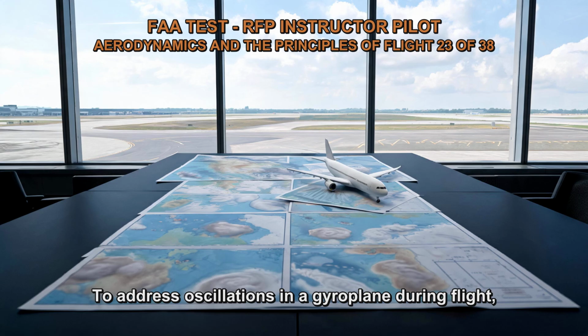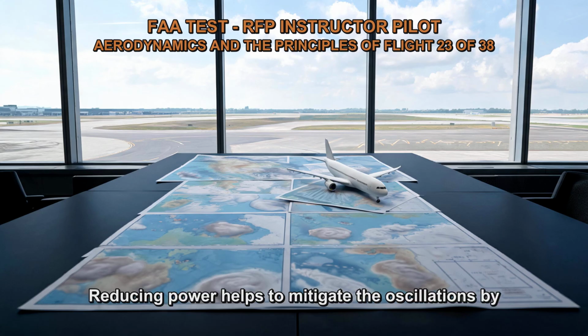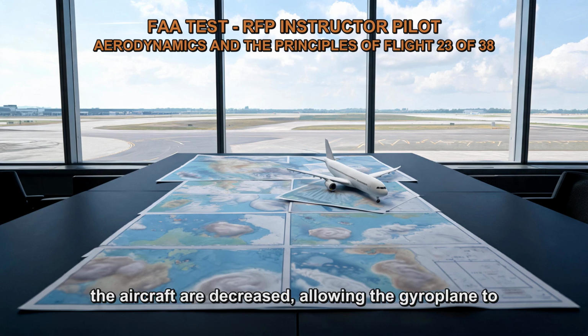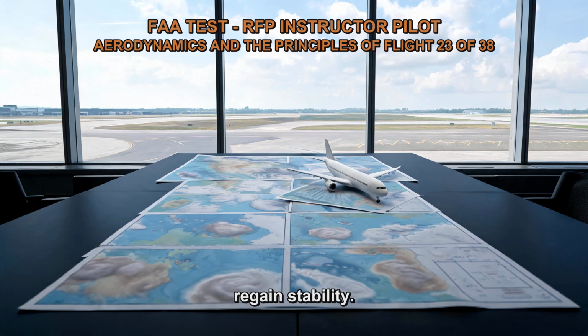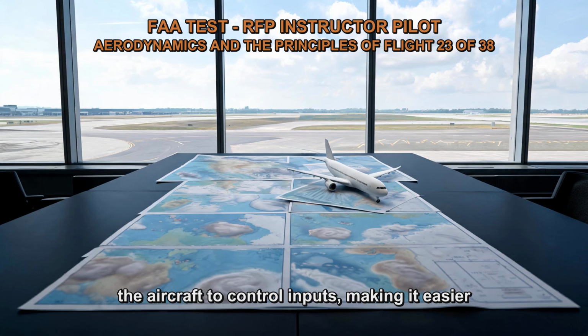To address oscillations in a gyroplane during flight, the first action that should be taken is to reduce power. When a gyroplane starts to oscillate, it usually indicates an unstable flight condition. Reducing power helps to mitigate the oscillations by reducing the overall thrust and speed of the aircraft. By reducing power, the dynamic forces acting on the aircraft are decreased, allowing the gyroplane to regain stability. The reduction in power reduces the responsiveness of the aircraft to control inputs, making it easier for the pilot to regain control and dampen the oscillations.